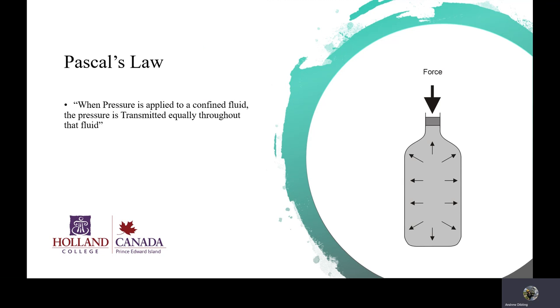And Pascal's law is something that we use, like I said, on things like bottle jacks or systems that don't have a pump. It's a sealed amount of fluid, a finite amount of fluid within a container, and then we just move that fluid within that container around, and as a result, we get the energy that we want where we want. Okay,